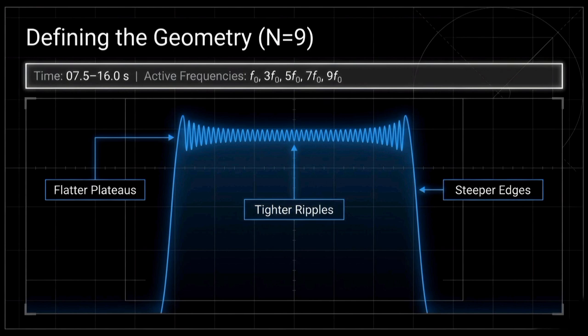No, we don't. The source specifically points out these Gibbs-style ripples at transitions, these extremely fine, tight, vibrating ripples localized right at the edge. That is known as the Gibbs phenomenon. It's actually named after the American physicist Josiah Willard Gibbs, who mathematically described it back in the late 19th century. Okay, but why does maximizing the sharpness inherently create this localized chaos right at the edge? Like, if we are adding higher and higher frequencies to perfect the square, shouldn't the edge get cleaner?